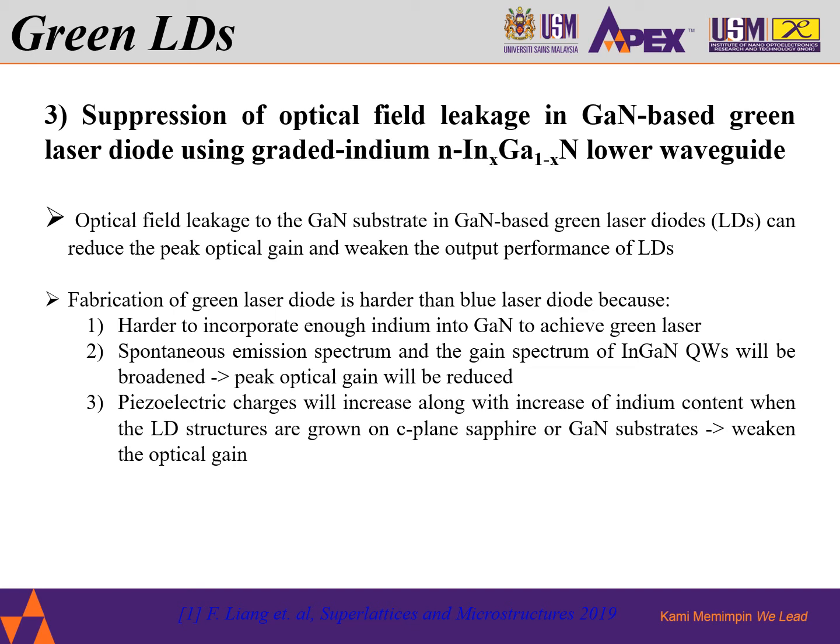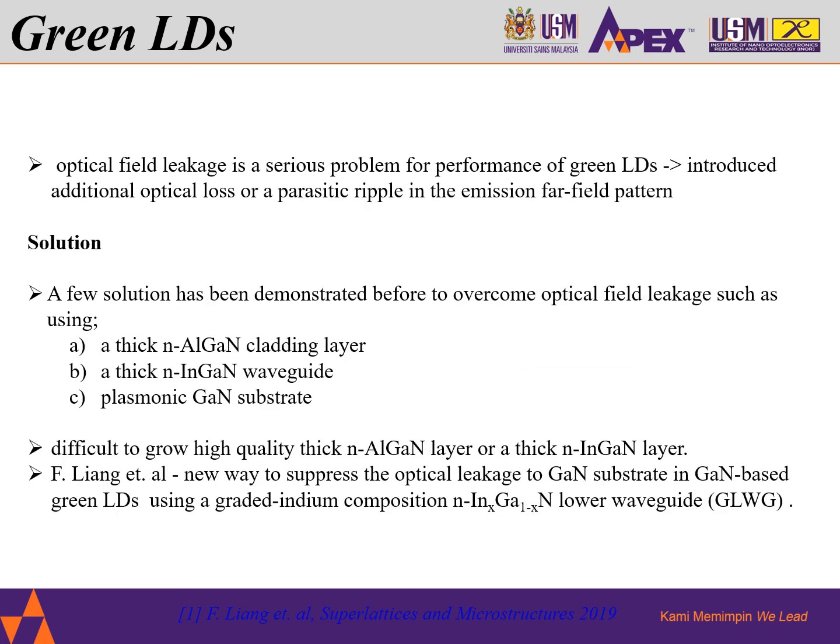Piezoelectric charges will increase along with the increase of indium content when the LD structures are grown on C-plane sapphire or GaN substrates. This results in the weakening of the optical gain. Optical field leakage is a serious problem for the performance of the LDs, as it introduces additional optical losses or a parasitic ripple in the emission far field pattern.